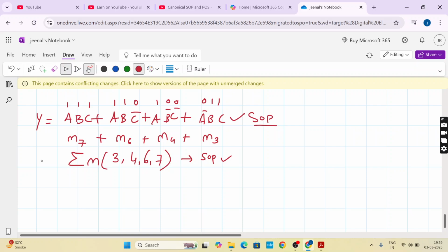If you are given this equation, you should know these are the min terms that represent it. Once you know the min terms, you can make a truth table. Wherever you have decimal 7, 6, 4 and 3, that output will be 1. All the other outputs will be 0. Once you know the equation and the truth table, you can create one from the other and implement it. Further, we are going to see how to reduce those equations using K-maps and then implement a reduced form of the equation. For the time being, please try and understand how we represent these equations.